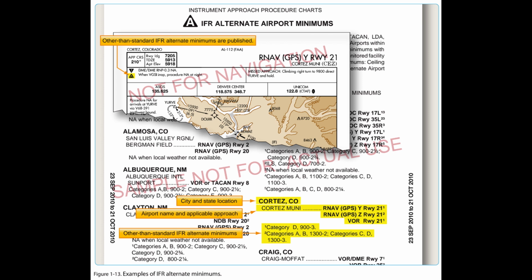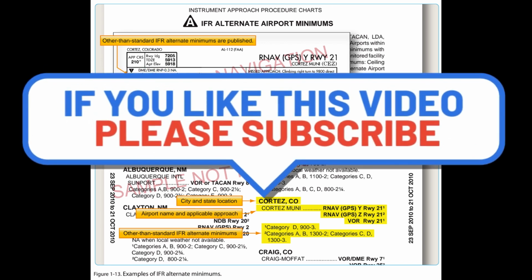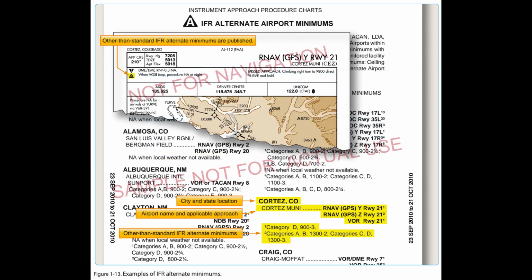For example, airports with only a global positioning system, GPS, approach procedure cannot be used as an alternate by TSO C129 or C196 users unless certain requirements are met, CAIM, even though the not applicable has been removed from the approach chart. For select area navigation, RNAV, GPS and GPS approach procedures, the not applicable is being removed so they may be used as an alternate by aircraft equipped with an approach-approved wide area augmentation system, WAAS, receiver complying with TSO C145 or C146, or TSO C129 or C196 meeting certain requirements, CAIM.